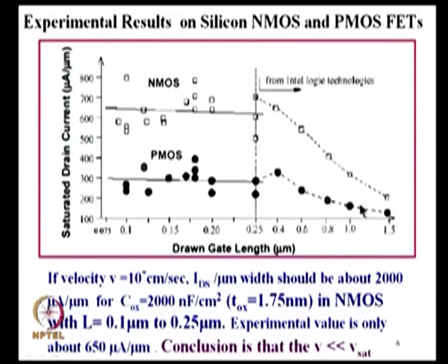You see, you keep on reducing the channel length. The X axis gives you the channel length, the y axis gives you the saturated drain current, ID sat. That is after the drain current is large enough. So, as you keep on reducing the channel length, this is for different MOSFETs, shorter channel, shorter channel, shorter channel.